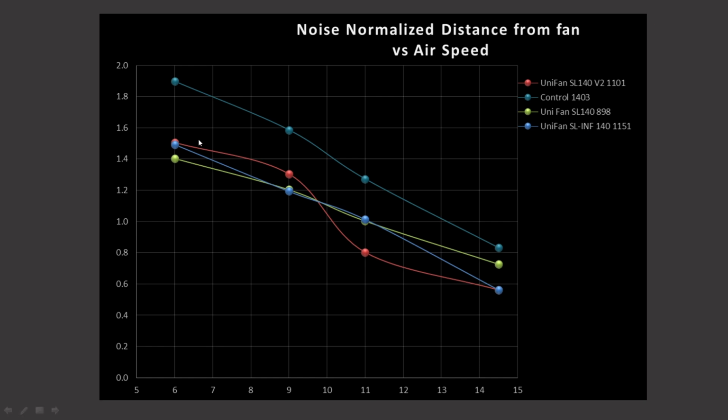So I have what's called my control fan. It is 3 parts A12x25 and 2 parts A14, both Noctua fans, both very good in their respective categories. By combining these two fans, I hope to create a great composite fan, effectively a 130mm class fan, because 120s tend to do better at the 6 and 9 inch mark, while larger 140s tend to do better at the 11 and 14.5 inch mark, where larger diameter fans fill the case volume with air more effectively than the smaller fans.